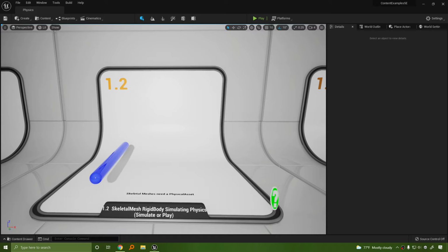This element is to simulate a skeletal mesh. Skeletal meshes, which we'll talk about in the future, can only be created with external software or if you use the rigging toolkit inside of UE5. But typically speaking, the documentation would prefer that you rig characters outside, either DAZ or 3D Studio Max or Maya. However, their collision is going to be set up in Unreal Editor. So when importing a physics asset, you can automatically create an object when you import if create physics